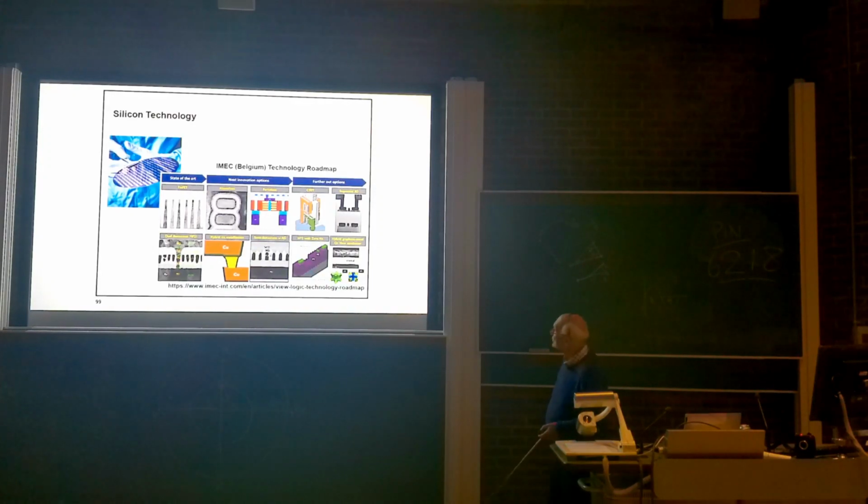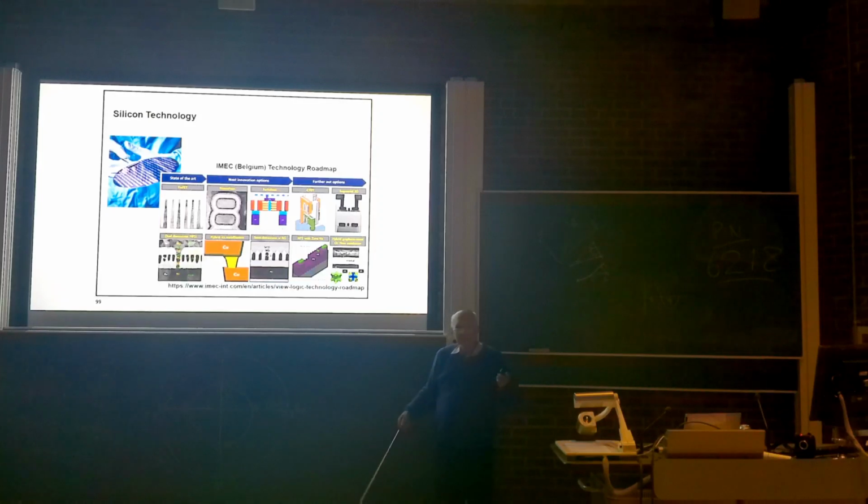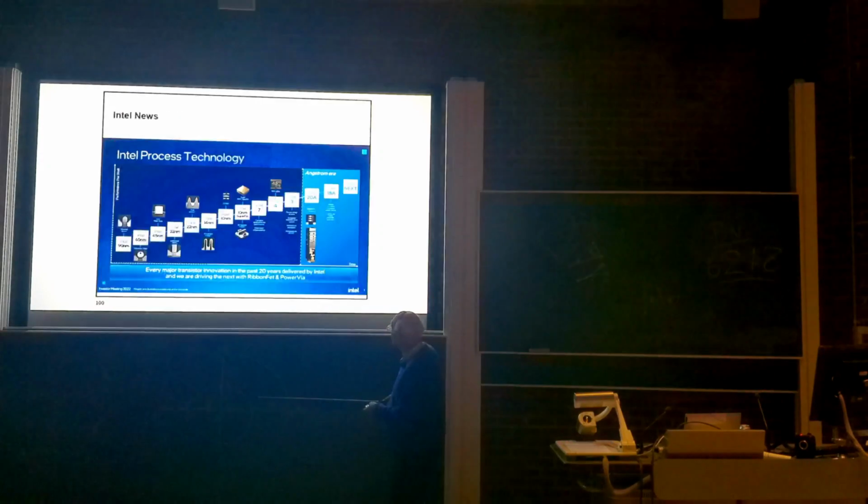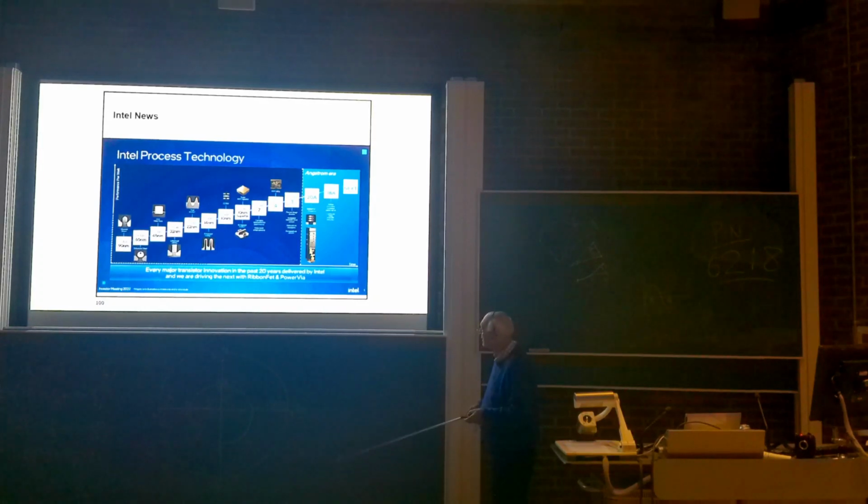Right, silicon technology. This is actually a slight change of direction. It's what's happening about the technology, the various things. I'm going to move on fairly fast, but roughly, perhaps we'll just look at a thing called FinFET, which means you actually have a fin going up, and the transistor is made of the fin, which actually has two sides. So the gate is a two-sided thing, so it can flow across in a very compact way. And then I think there are some better pictures of FinFET later.